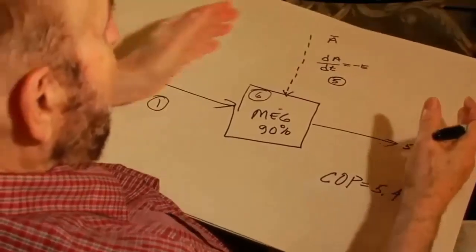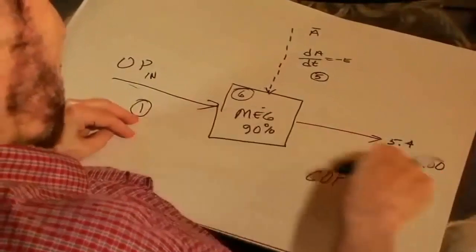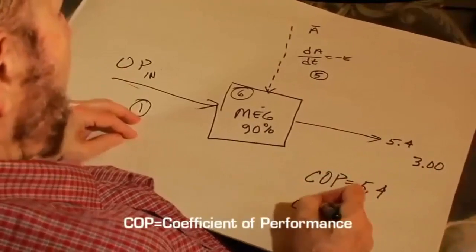This is just an energy converter. Now when I add another stage on here to convert that into a standard kind of power form, either direct current at a certain voltage or AC, I will have an inefficiency there. Maybe I'll cut this down. Let's do real bad. Let's cut this down to 3. Let's lose 2 points, almost half of it. We didn't have too efficient a conversion, let's say. We were sloppy. We didn't go get the state of the art. We're much better than that. But even with the bad one, once we have it set to run loads, and actually running lights and motors, we're putting in 1 part, we're getting out 3 parts. We have a 3-to-1, a 3.0 COP practical.